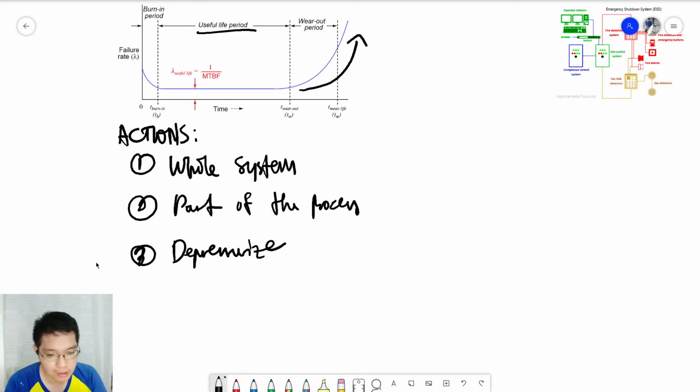For example, if the malfunction is occurring in a line or a component of the system that handles high pressure, then before you can work on that high pressure component, you must first depressurize and then shut down.